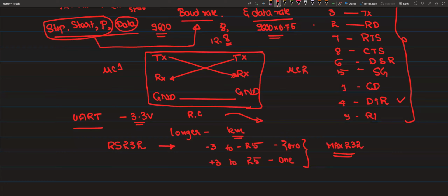And in UART, I said it is 8-bit data which we are transmitting. For example, if you want to transmit the character A, it will find the ASCII value of it, and that ASCII value will be communicated. Usually that is 8-bit. So that is about the serial interface. Tomorrow we will look into how we can implement this serial interface using 8051.